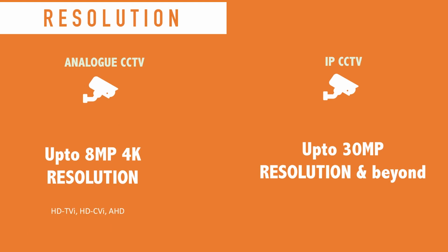Now if we compare the resolution, both systems can actually do 8 megapixel, which is 4K high definition. We get a lot of questions from people who think analog is restricted to non-HD, which is not true. Analog can actually go up to 8 megapixel, which is a 4K resolution. The types of signals you might hear of are HD TVI, HD CVI, and AHD. These are the protocols that are used to send a high definition signal over a cable.